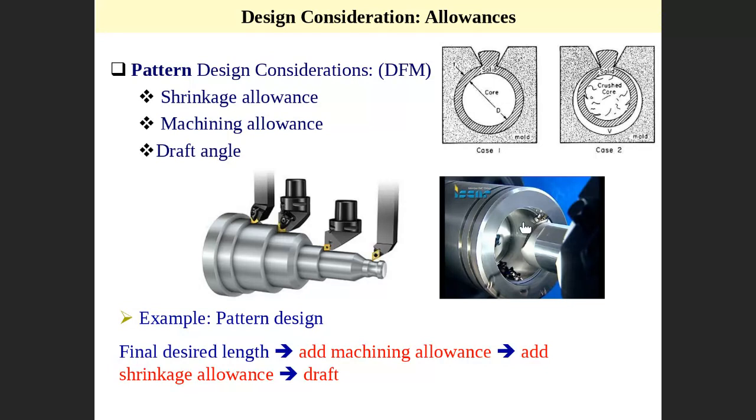Remove two layers, outer layer and inner layer, because especially in sand casting, diffusion happens and some sand gets trapped inside. Then you get an outer layer and inner layer that are a mix of liquid and sand, which you need to remove. So this is the machining. We remove the outer layer and inner layer.